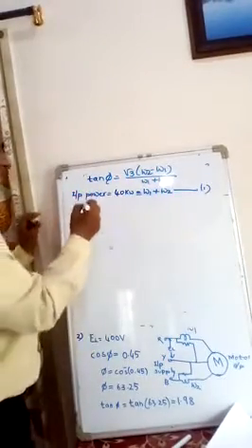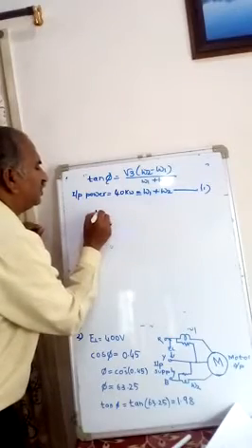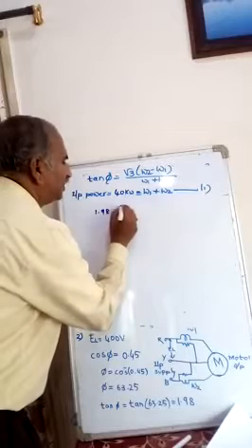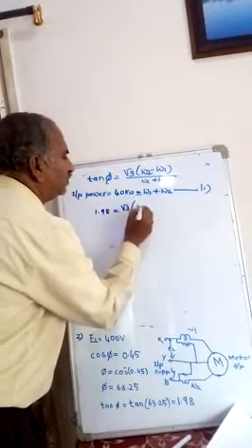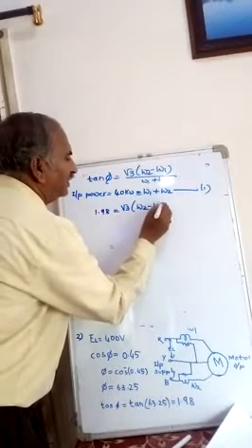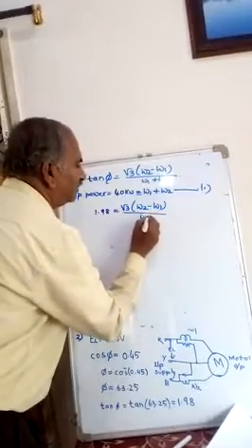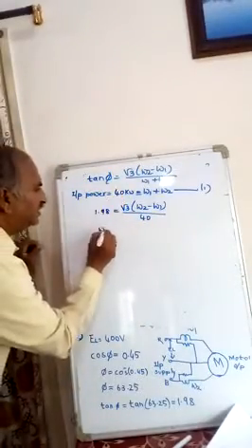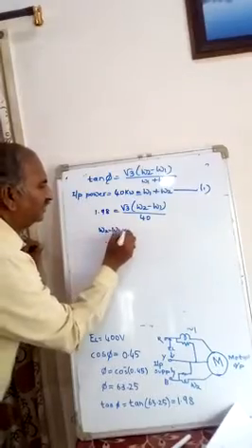Then you can go for substitution in the equation. Tan phi is 1.98. So it is root 3 of (W2 minus W1) divided by (W1 plus W2), which is 40 kilowatt. Hence you can estimate very easily W2 minus W1.